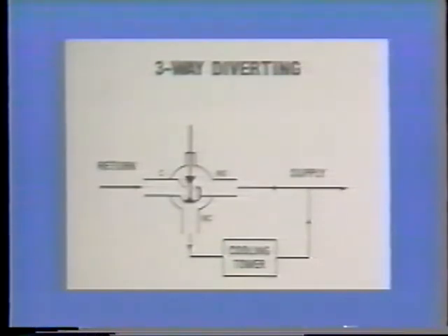This is a three-way diverting valve. In this particular application, note that the flow to the valve enters the common port and exits through either the normally open port, which bypasses the cooling tower, or through the normally closed port, which goes to the cooling tower.